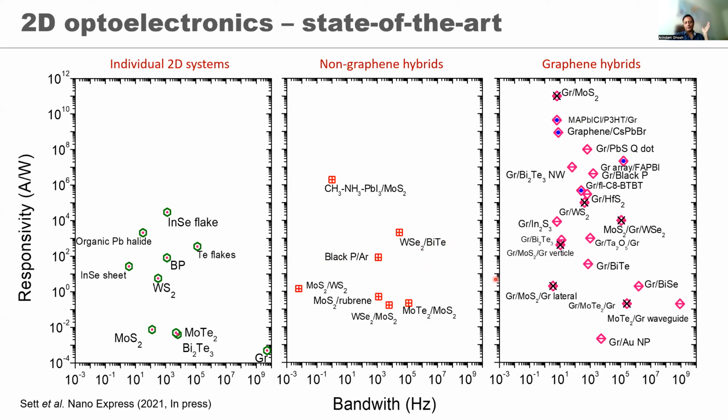However, if you partner graphene with many of these, you can see a clear change in the overall optoelectronic activity. There is a very large photoresponsivity when you use graphene as a partner, and I told you why: simply because graphene can conduct electricity very fast. As a result, the gain, that is the number of electrical charges you can create in graphene while you are waiting for the electron-hole pair to recombine, is very, very large, and graphene's mobility plays a key role in that.